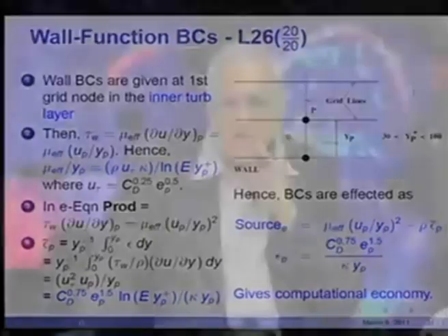In the next lecture, I will consider further refinements for situations in which the eddy viscosity models do not quite apply in a precise manner, and therefore, one has to turn to the modeling of the turbulent stresses themselves, or obtaining turbulent stresses through transport equations for ui prime uj prime.